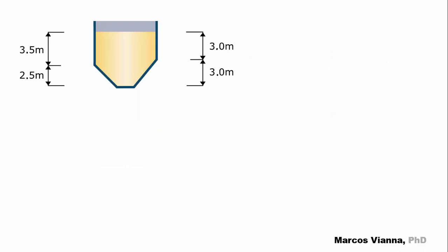Now we'll see a very practical problem about pressure diagrams. Pressure diagrams are the graphical representation of the variation in the intensity of pressure over a surface. It's used to calculate total pressure force and center of pressure for a submerged body, as we'll see in other videos. Engineers who deal with structural calculations love pressure diagrams.